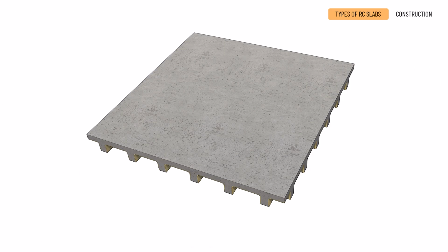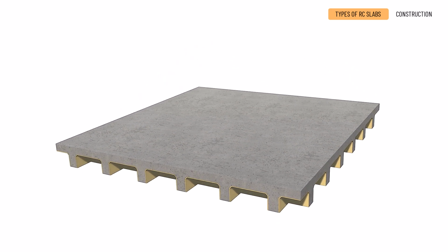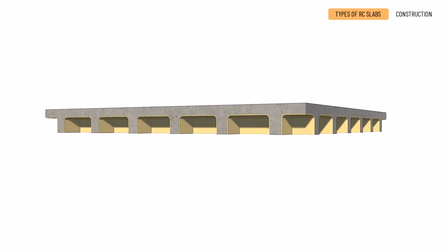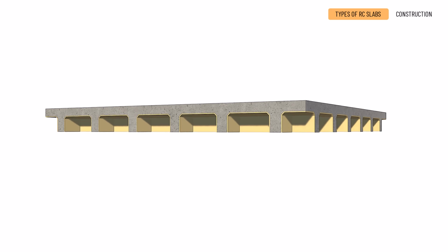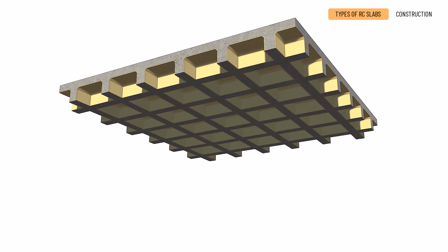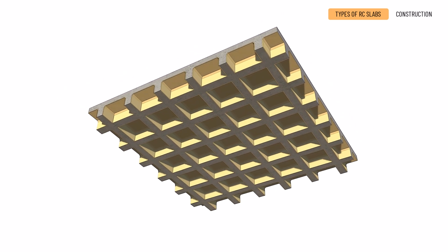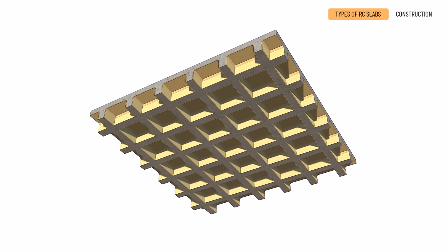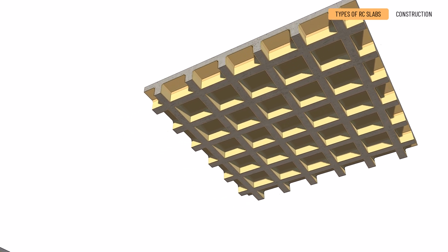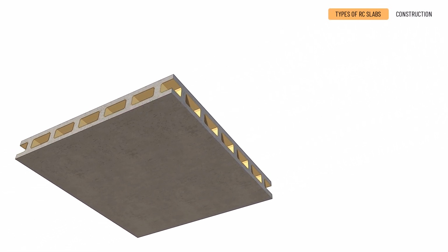Waffle reinforced concrete slab. A waffle slab is a network of perpendicular ribs. When installing formwork, plastic exclusion elements are inserted which can create coffers opened from below or closed with hidden cavities within the slab.